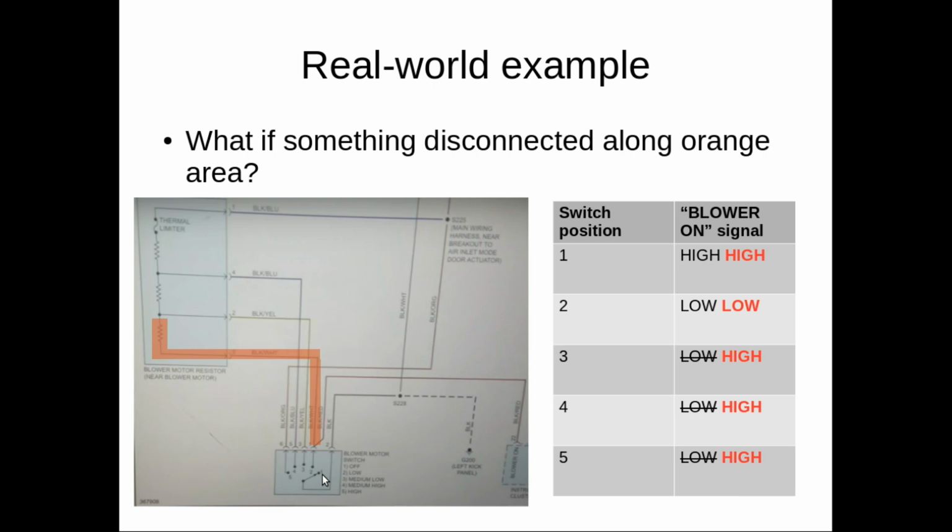If switch position is 1, then the terminal is completely disconnected, and as we've discussed before, it should register the high signal. So that is consistent with what we observe. When the switch is in position number 2, it will ground the terminal and we will get signal low.